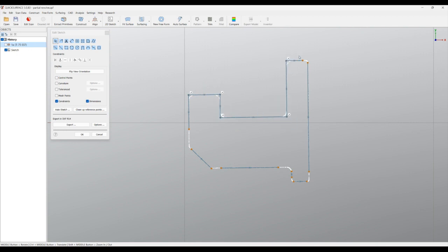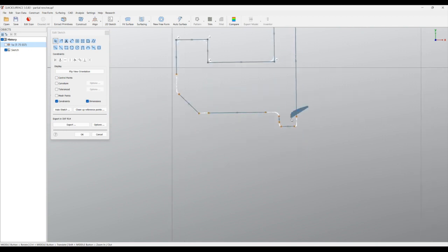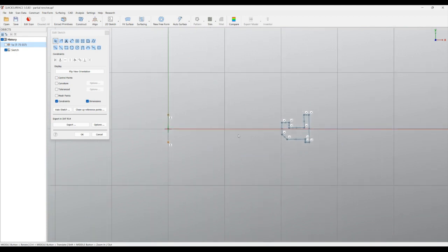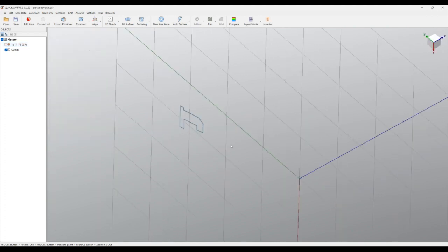This will help you quickly to close your sketch. And so far I created my profile. Because I used the option for revolved surface when I created my shape, you see that there is a construction line here, and I can press OK.